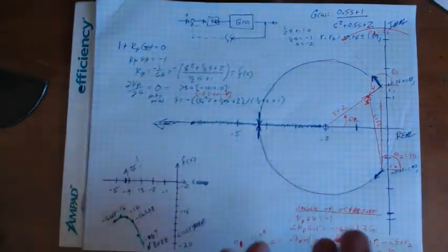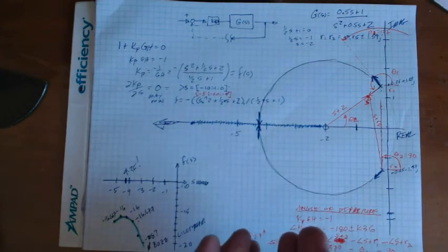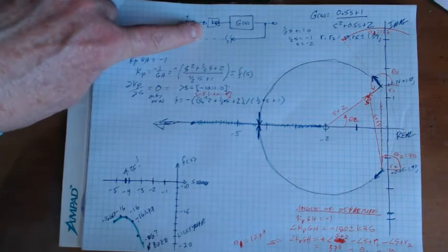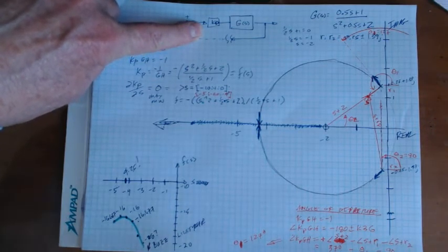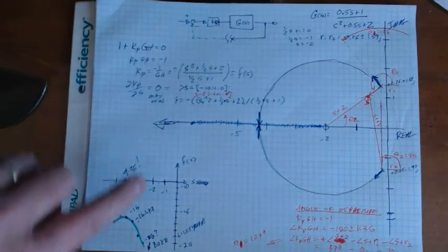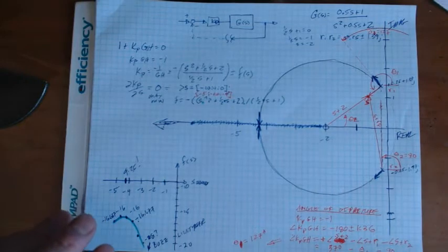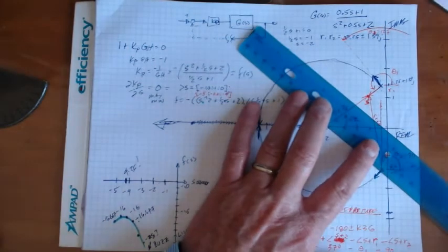So this curve that I have here represents any place in the S-plane where I can put the roots of the characteristic equation using this control structure, which is Kp. And again, I can choose many different things, but why not just choose zeta equals 0.707?